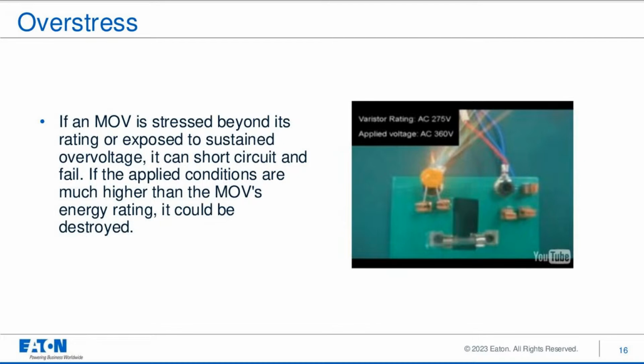One of the drawbacks of MOVs that must be addressed when designing them into protective circuits is their limited life. Each surge event generates heat within the MOV. Repeated surges cause cumulative thermal stress, which can lead to the breakdown of the metal oxide grains and the binder material. As the MOV degrades, its ability to return to a high resistance state after a surge diminishes. This leads to a decrease in the clamping voltage and an increase in the leakage current, which eventually leads to a short circuit.